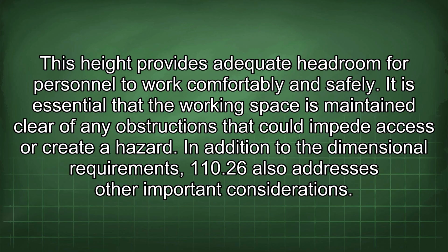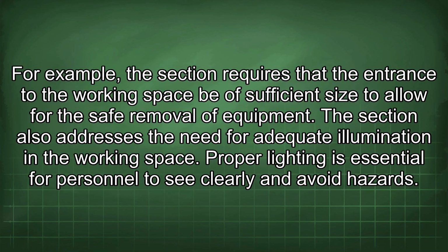In addition to the dimensional requirements, 110.26 also addresses other important considerations. For example, this section requires that the entrance to the working space be of sufficient size to allow for the safe removal of equipment. The section also addresses the need for adequate illumination in the working space. Proper lighting is essential for personnel to see clearly and avoid hazards.